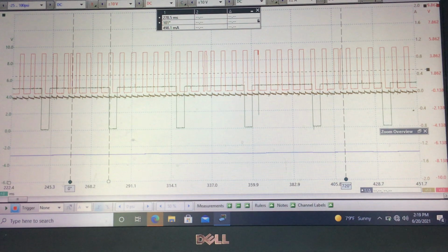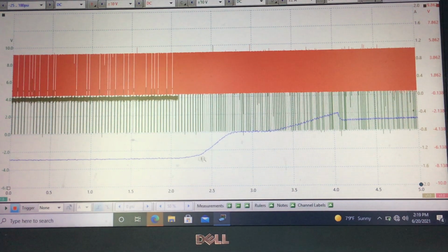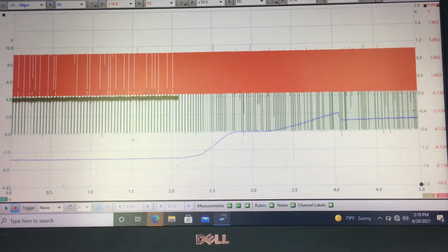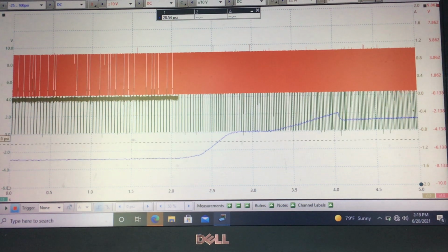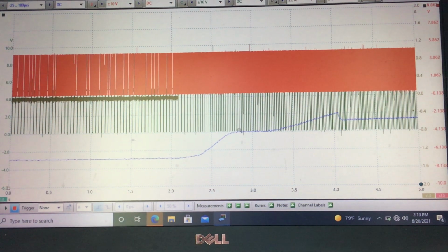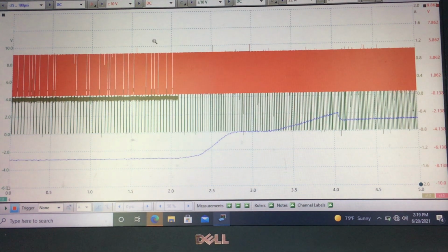So anyway, let's get back to normal, and we can see our oil pressure at idle is okay, about 28 and change at idle, and you can see the oil pressure ascending as I get into the throttle. Right there, it looks like it clips. That may be the relief valve at about 90 psi. Nonetheless, we'll analyze that more in depth as we go down the capture.